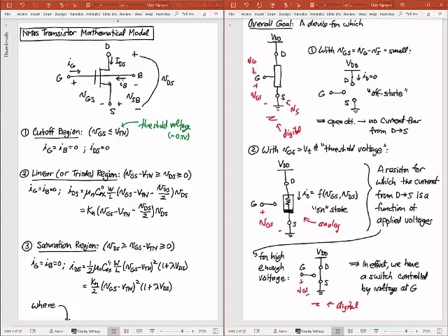In fact, let me put the transistor we want back up here. When I have this, I effectively have this equivalent circuit on the right. Okay, so the MOS transistor does exactly what I want it to do if that thing on the right is my definition of a transistor. Okay, but if I raise my voltage such that VGS minus VTN is greater than 0, but is also greater than the voltage VDS that I put between the drain and source,